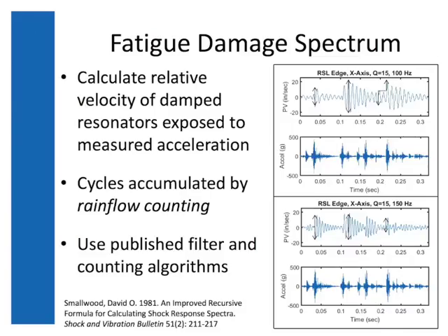So how does this work out? I've provided here an acceleration trace which is intentionally not from a shaker. This is from an RS table, so repetitive shock. And if you don't know the resonant frequency of your product, but you nevertheless want to calculate stress cycles, you could just pick a number of resonant frequencies. I've picked here 100 Hertz and 150 Hertz.